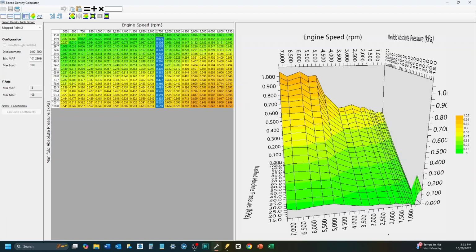So for my columns, I know I need to have RPM is what I'm logging, and it needs to have, and this is really important, prick your ears up if you have been sort of drifting, looking at your phone or something, right? This is important. This scale needs to match what is in your histogram, so it logs the percentages accurately against each cell. So when you make your correction, it's touching the same cell with the same basis of percentage, okay?